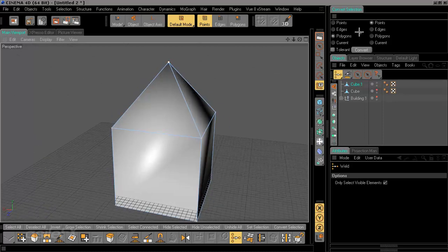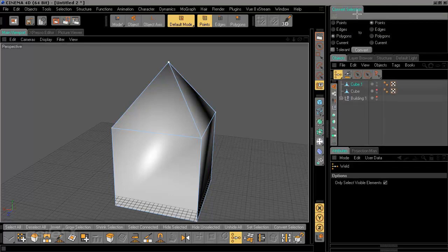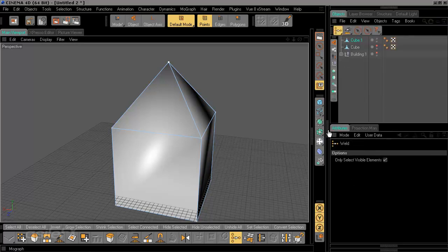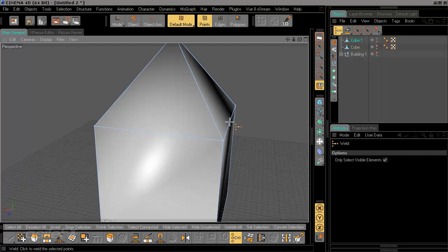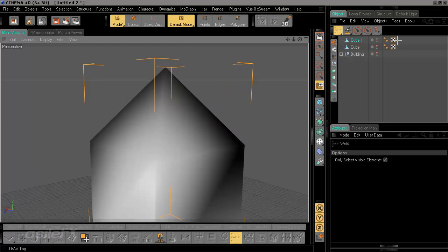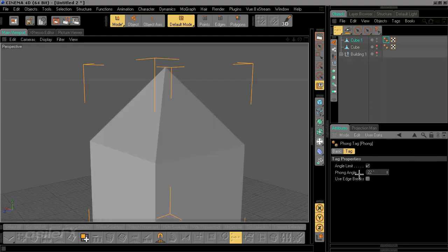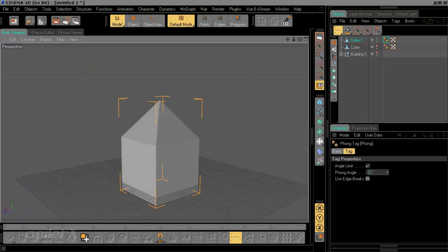And that's kind of an easy way to create this type of roof. And now if I want to hide this, you can just hold down Control and then click on that little section right there, or if you have something without the tab, you can just click on that little bar that's showing up with the points in it. So that's a pretty easy way to create another building shape.